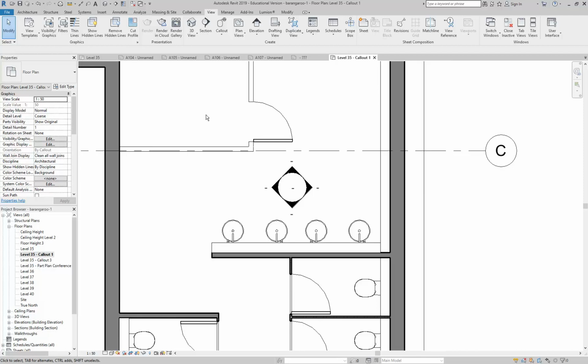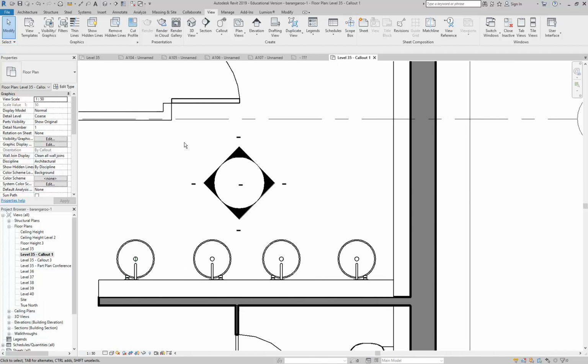So yeah, it helps, doing it with AutoCAD, you're forced to deal with it. Otherwise, the guys who just use Revit, it just does this stuff for them, and even when I tell them, see how the text is changing size when you change scale. It's relative to your objects, it's not the print scale that's changing, and they just don't get it. So I think it's still really helpful to know AutoCAD. But it makes you very grateful for Revit.